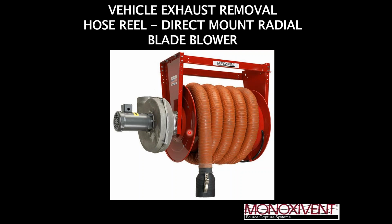I can put a switch on here called the DMS HR switch, or direct mount switch to hose reel, so that when the kids either bring the hose down motorized or they pull it down with a spring hose reel, the fan starts automatically. And when they let the hose retract, the fan turns off automatically. So the idea there is we've taken some of the decision making away from the kids, and to ensure that if they pull that hose down and they attach it to a running vehicle, the fan is on and operating, and we're eliminating all of that exhaust.